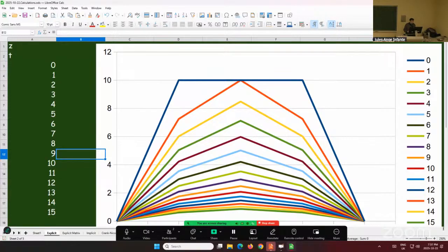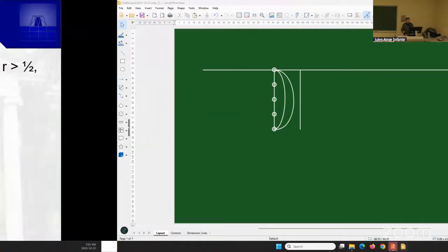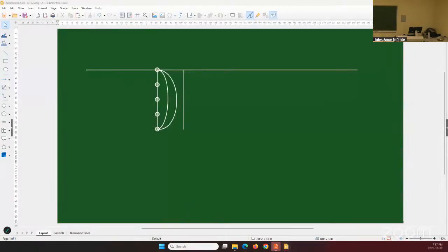Before we go to the implicit, we get the shape that we wanted. Obviously, that's tipped over on the horizontal, but it's the shape we wanted. Before we move on, we're going to look at how we expressed this. This is a memory efficient approach because I have one row that has the data of the previous step and I calculate the next step. If I was doing this programmatically, I could just switch the content of the two rows and just need twice the number of nodes in terms of RAM.